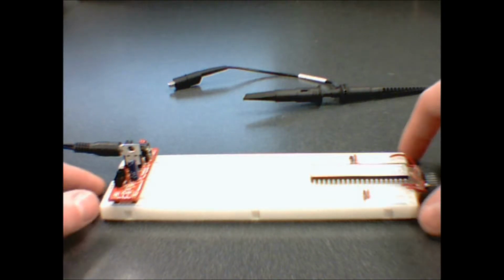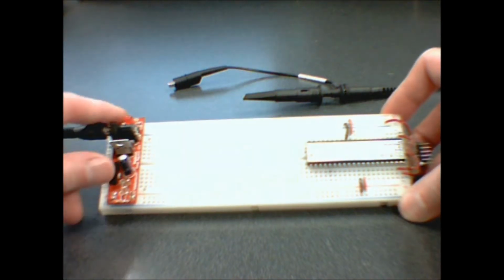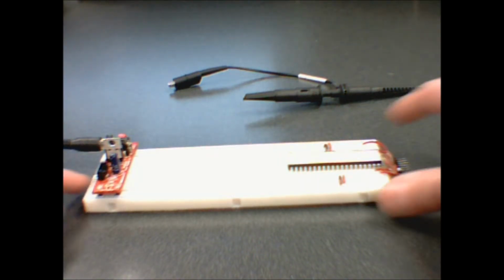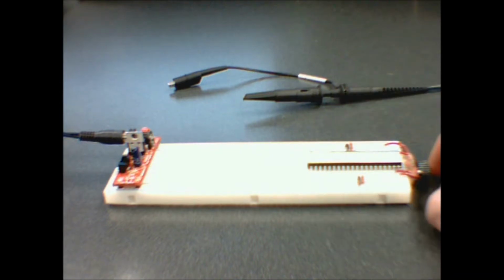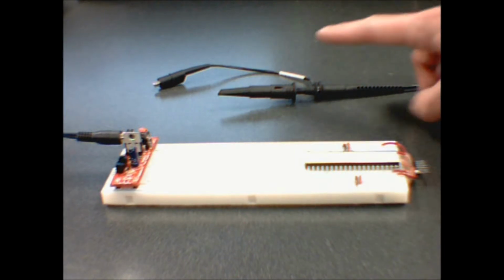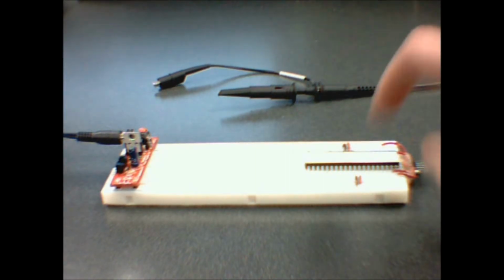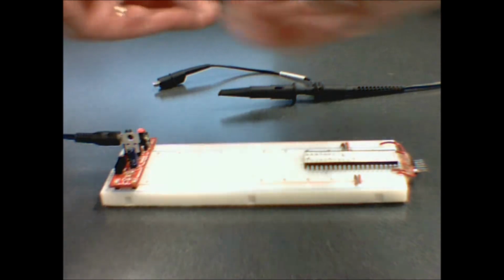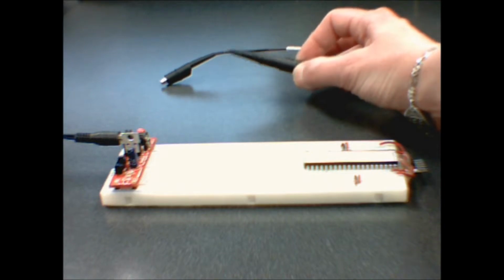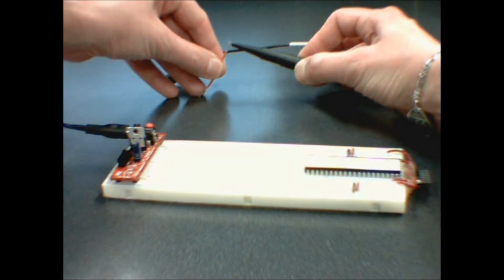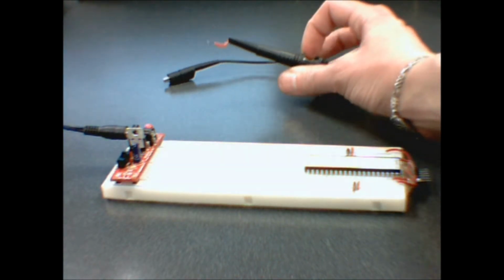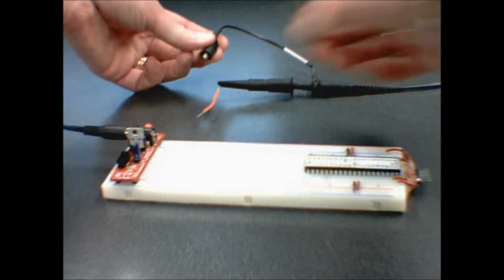So to measure the clock output of your chip, first of all, you've got to power the chip, so turn that on. You're not going to be programming anything, so you don't need the PICkit here. And to connect what we're getting out of the chip into the oscilloscope, we're going to use this little cable here. The way in which you connect the oscilloscope via this cable to your breadboard is you get 2 little pieces of wire, and this end here has a little sleeve, and if you pull this back, there's a bit of metal there, a little hook. So you can hook a piece of wire in there, release the sleeve, and that clamps the piece of wire. And the other end is just an alligator clip, like so.